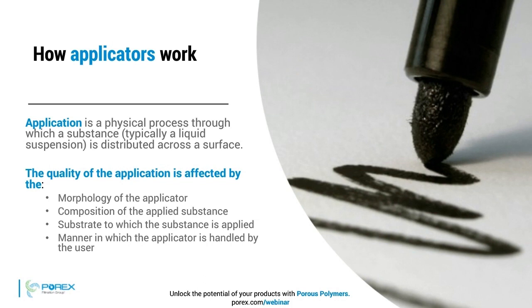The quality of the application is affected by the morphology of the applicator, i.e. what is the capillary pull in the applicator itself; the composition of the applied substance, which means what is the surface tension of the liquid, what is the viscosity, what are the solvent types used in the liquid; the substrate to which the substance is applied, again capillary pull and roughness of the surface on which we are applying the liquid; and finally the manner in which the applicator is handled by the user, which means the speed and the pressure applied by the user.